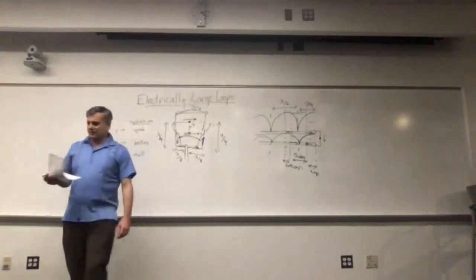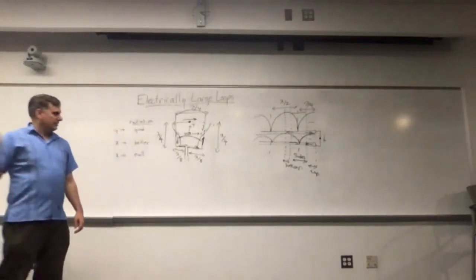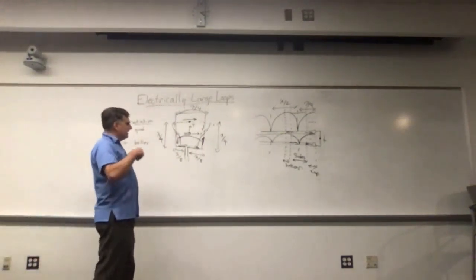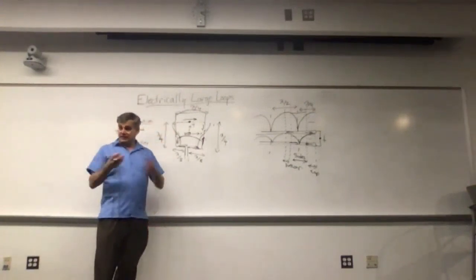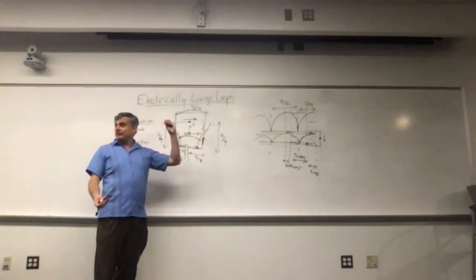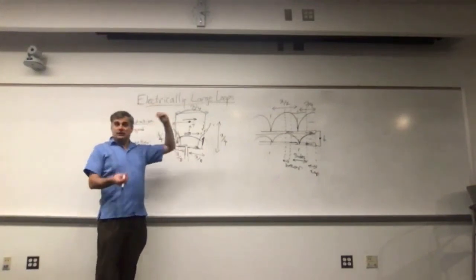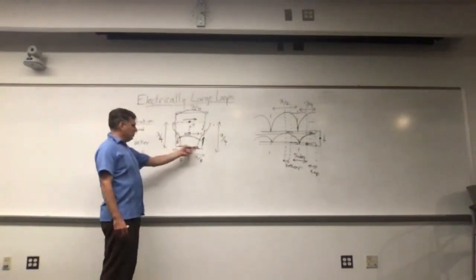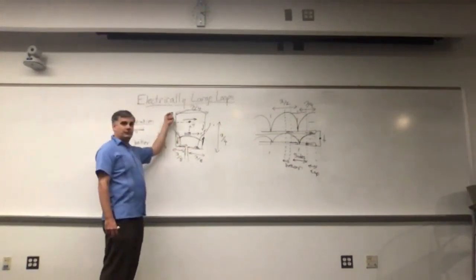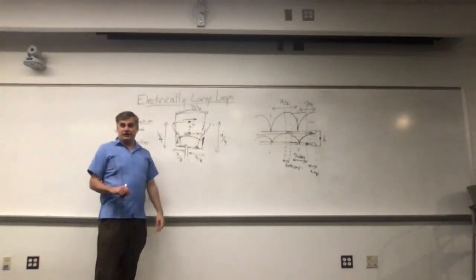What's interesting about the electrically large loop antenna is that there are repeated resonances, really almost just like a dipole antenna that you keep adding half wavelengths to get bigger and bigger. So for example, you can make a 2 lambda loop, which looks very funky.